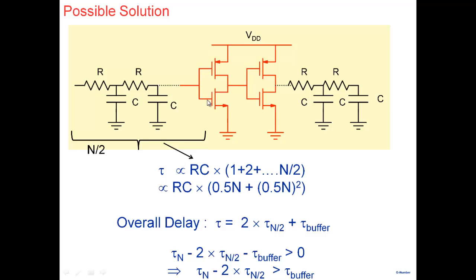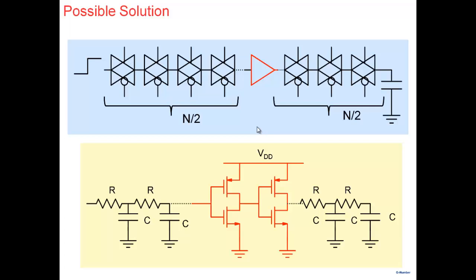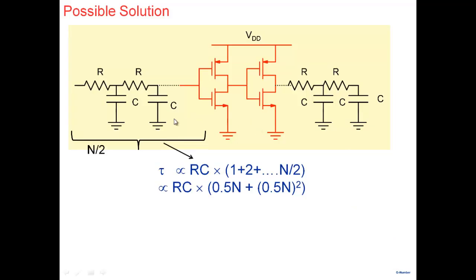Then a fresh signal starts from here, from VDD. A fresh signal from VDD, so you will see a pull-up resistor and then it starts like this. So the chain has been broken. The chain which was earlier one long continuous RC. So for example, if I look at a capacitor here, earlier a capacitor here would have seen this R and would have seen all these R's.